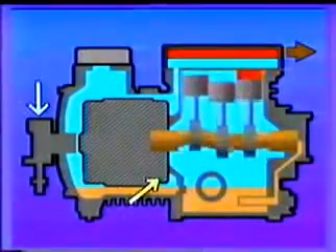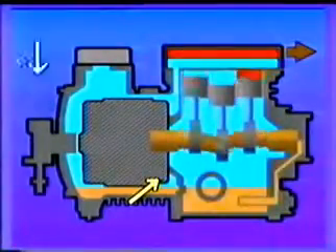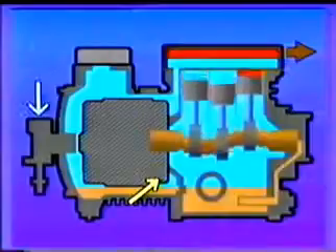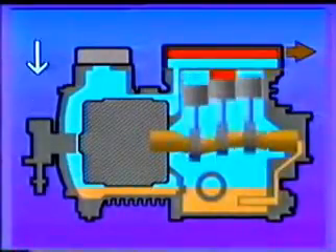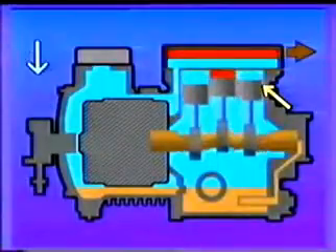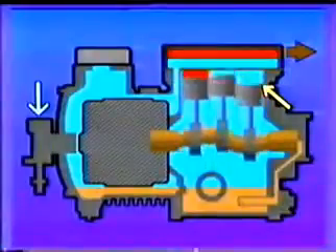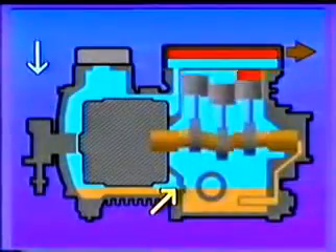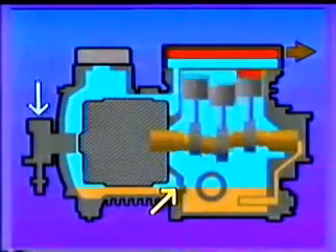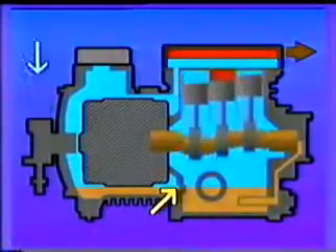And secondly, these fine iron particles may coat the end turns of the motor and cause an insulating effect or physically cut the winding, causing a spot burn of the motor. Another visible sign of overheating damage is caused by worn rings and pistons, allowing gas to blow by the piston and pressurize the crankcase. Even with a crankcase ventilating system, the excess crankcase pressure resulting from blow-by causes the oil return check valve to close. This prevents oil from returning to the crankcase from the motor compartment.